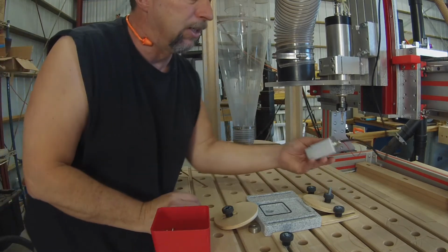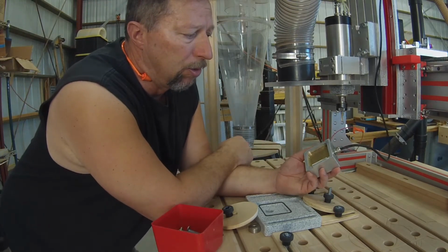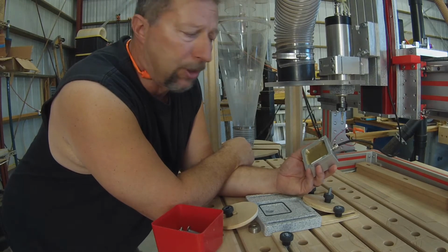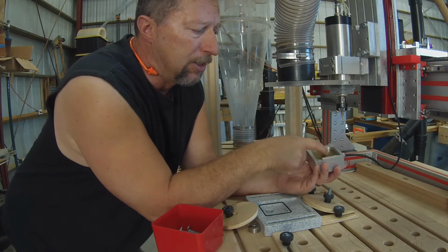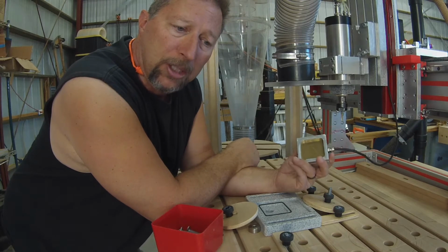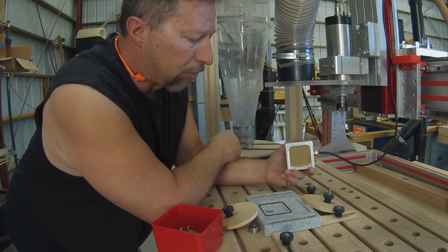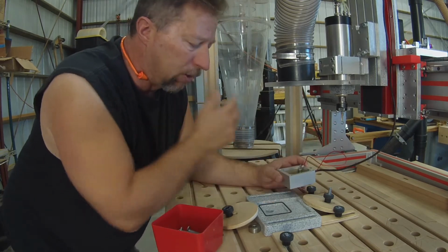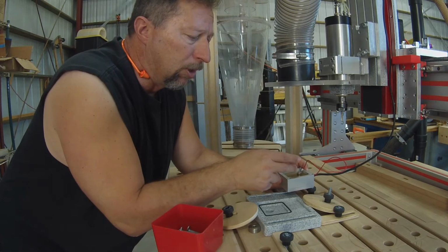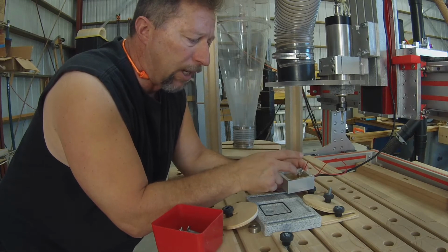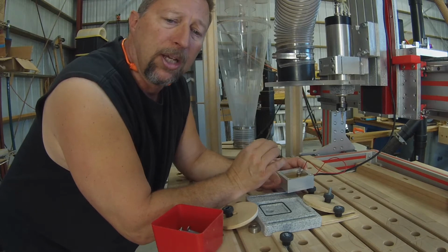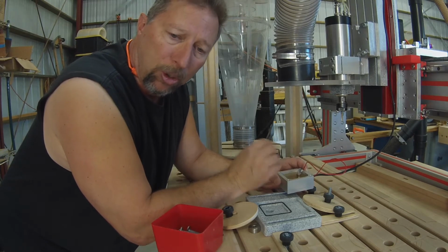Now what I have is a zero fixture, a zeroing plate that is from CNCrouterparts.com, and this one not only doubles as a Z-axis zeroing plate, but it also has the ability to zero the X and Y axis based on the corner of a piece of stock or something. And that's how I located it originally. If you noticed in the beginning, I put it on the corner over here, and I used it to locate Z0 as well as X and Y0 on the corner of the stock. And in my CAD program, I had set the corner of the stock as the work origin.